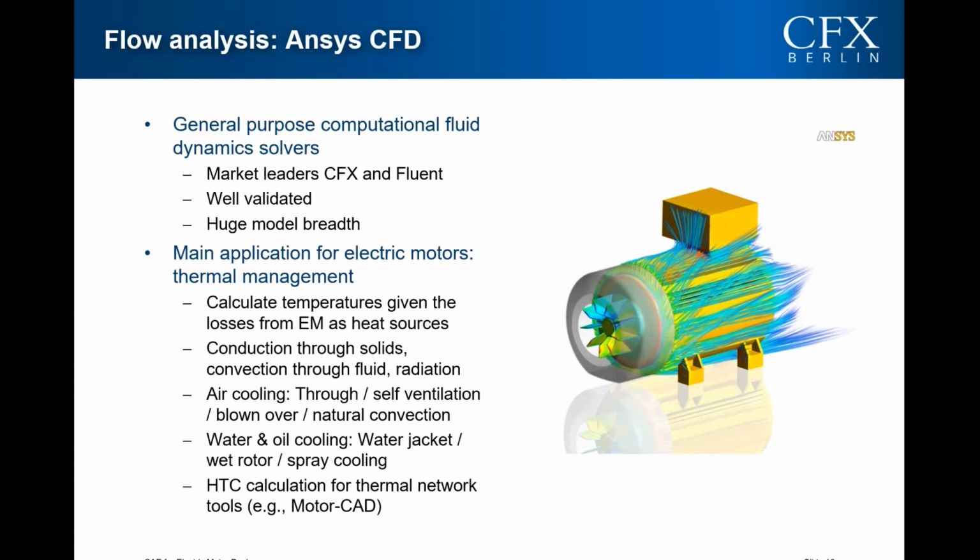We can model the distribution of heat fluxes given the losses from EM as heat sources, and we can calculate the resulting temperatures. Doing so, we can take into account the conduction through solids, the convection through fluid, or even radiation effects.